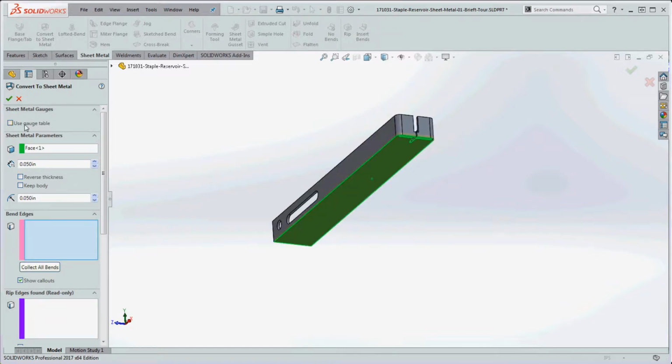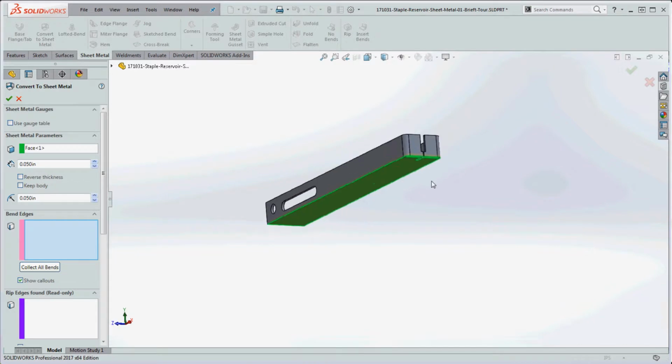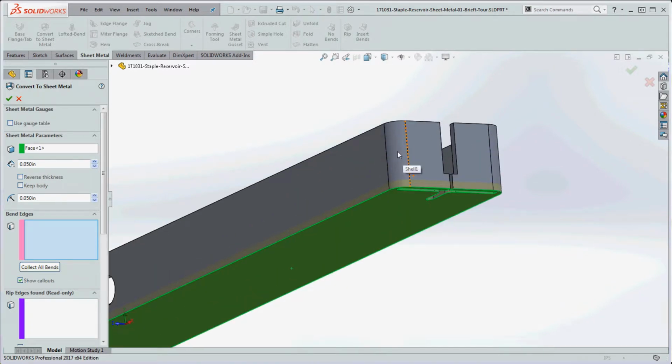And then we're going to go ahead and choose our parameters. So in regard to this fillet over here, it's 0.05 on the inside. But it always considers, when you put in a value in here, the minimum value. So you can't put a 0.05 on the outside where it actually comes down to 0 or less on the inside. It's not going to let you do that.